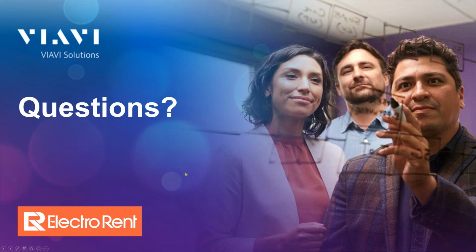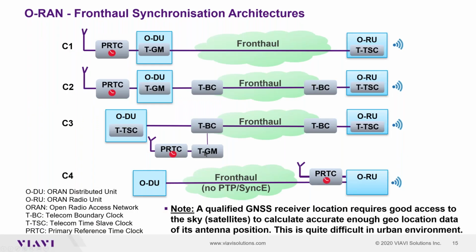Of course, if I understood correctly, when you have jammers or something which disturbs the GPS receiver, let me show it. I have here a GPS receiver, and if it's disturbed by any attacks, then of course you lose accuracy here. So if nothing is available, you have to go into holdover. Depending on the oscillator, you will introduce a drift, and this can at the end mean that you have an extreme degradation of performance.